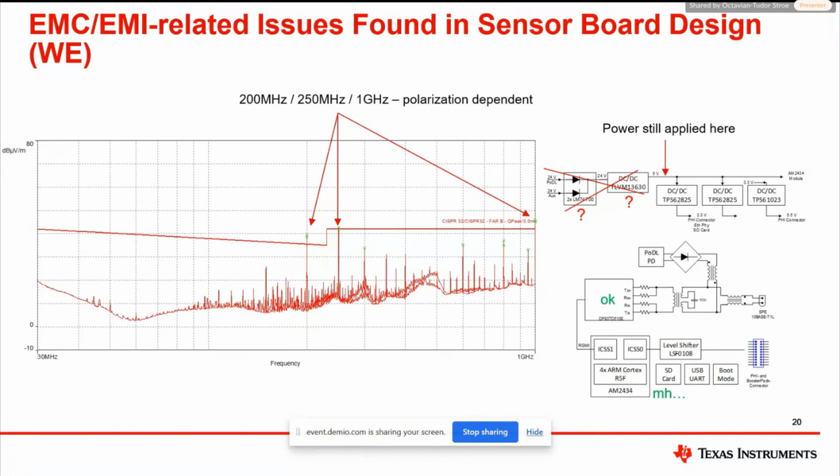Also, let's check the datasheet. The AM6442 MCU outputs a clock with a rise time of around 1 nanosecond. Checking the layout, we found out that the layout was not designed for this, and this very fast rise time was not accounted for. Also, there was some poor ground plane use around the SD card, and there were no series termination resistors on the SD card, and this could cause the high frequency communication between the microcontroller and the SD card to radiate.